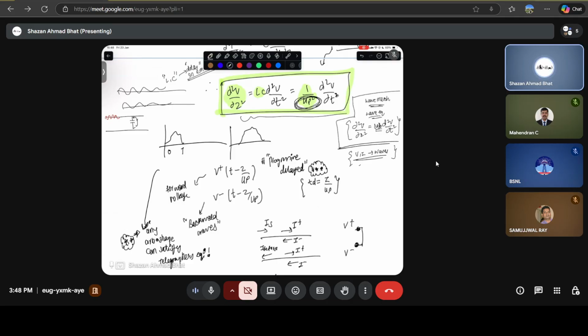If the charge gets stored, it is going to impede the motion of the other charges, other electrons, because at the end there are electrons flowing. That's going to cause a delay, and slow down the motion of this electromagnetic wave. That's why inductances and capacitances are the governing factors of the speed of the wave in the transmission line.